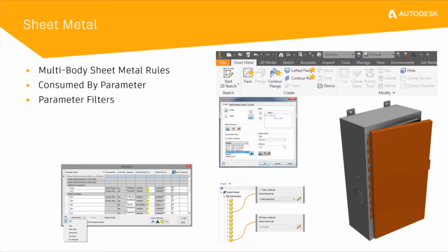So this allows our users to lay out a complete sheet metal design with multiple sheet metal thicknesses, multiple sheet metal rules for flat patterns, all in the same part file. Obviously, here's a parent part file, and you can from there do a make component, and you can link back to those sheet metal styles, and you can insert flat patterns for each of those. But again, this parent multi-body sheet metal part would contain all of the bodies as well as the different rules that govern them.